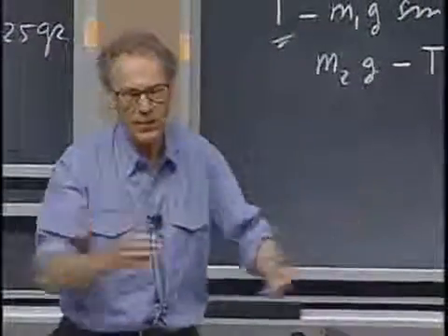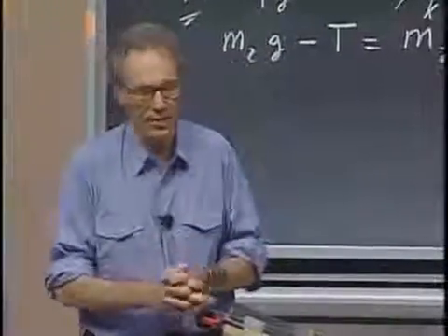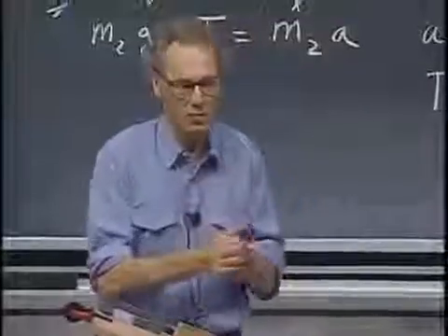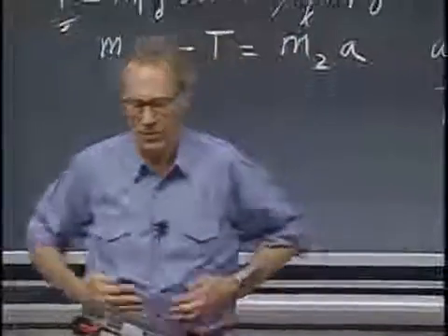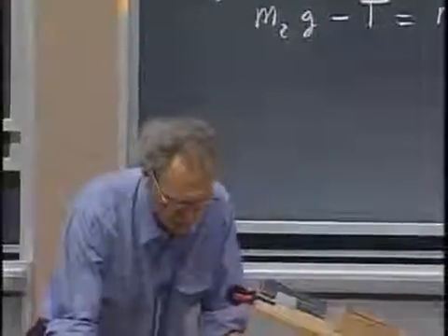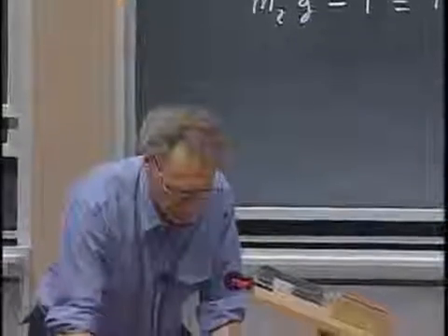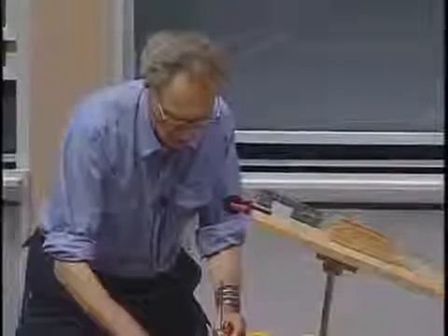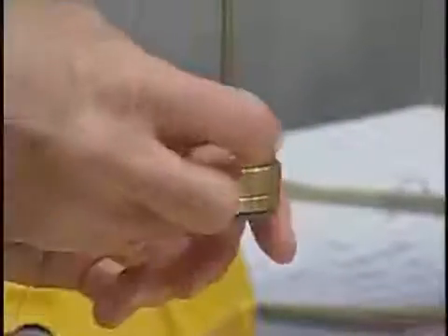Just because I've done it many times, and I know it could even be worse at times. The humidity could change in the room, and that could change the friction coefficient. Okay, we have 100 grams on it. We have 200 grams on it. 250, 260, 270, and it goes at 270.